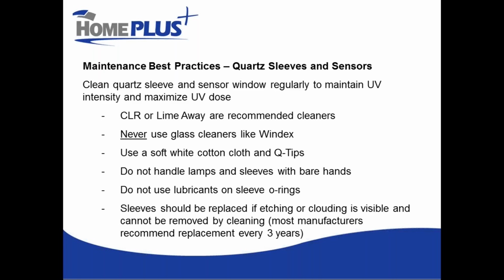Sleeves should always be replaced if there's any etching or clouding that cannot be removed by fairly simple cleaning. And the vast majority of manufacturers are actually recommending now to just replace your sleeves every few years. Many of them are even providing lamp-sleeve combos where you buy the lamp and sleeve together, and you're getting the sleeve for next to nothing. They're really trying to encourage that because they know it results in better UV transmittance.